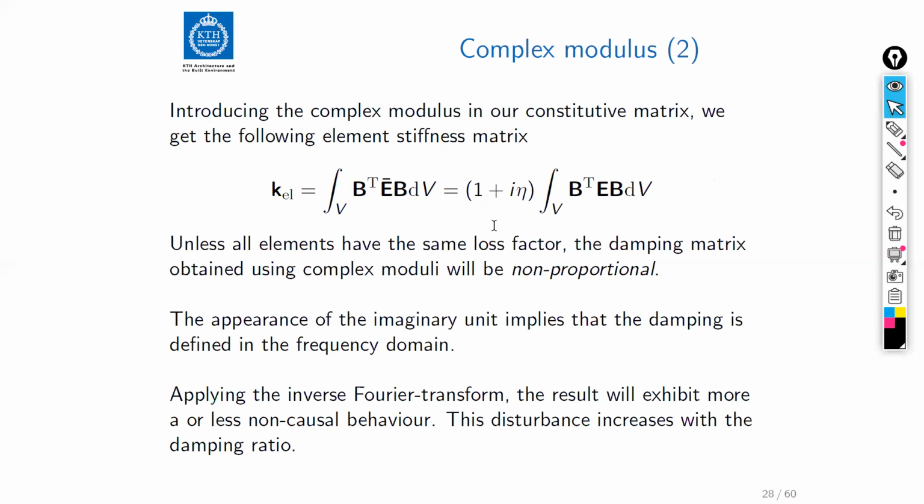This is, I would say, an artifact of the way that we construct damping in this way. So this only works well for weakly damped problems. The more damping we introduce in this way, the larger the non-causal effect will be. So this is something that one should keep in mind when one uses this complex modulus.